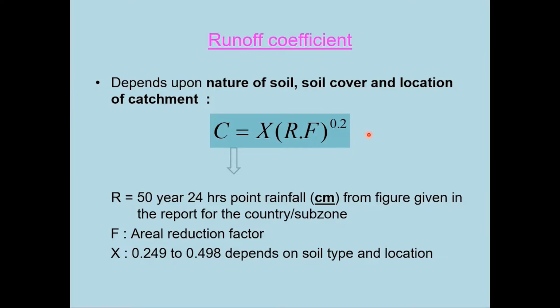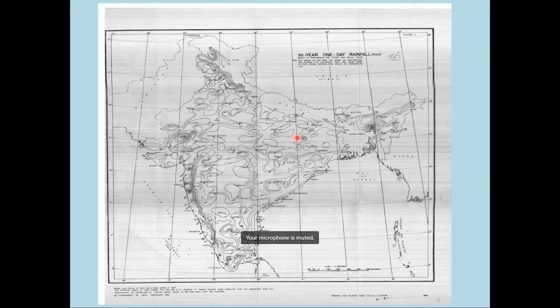Yes, sir. So, okay. So we will know about what is the rainfall. So how we will find out the 50-year rainfall? So for this, in the RBF report 16 and also in the different flood estimate reports, there are different maps which have been given for different subzones there, either 24-hour or 1-hour.